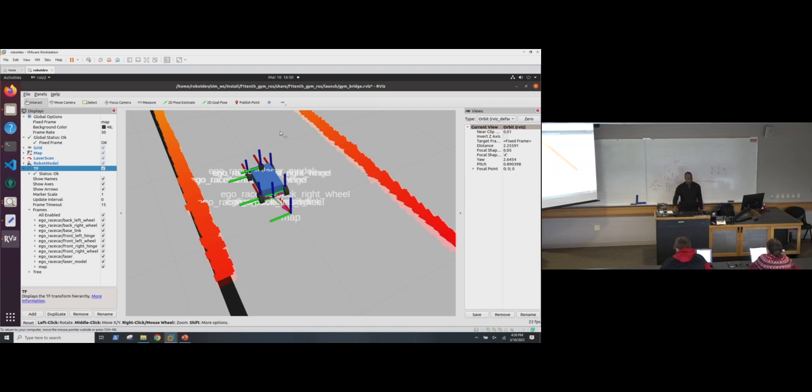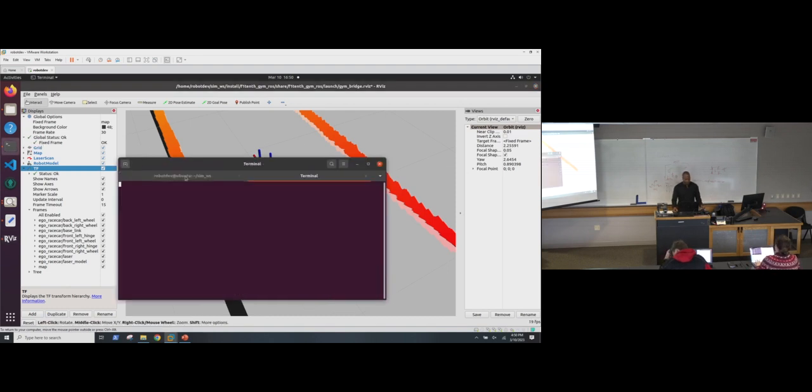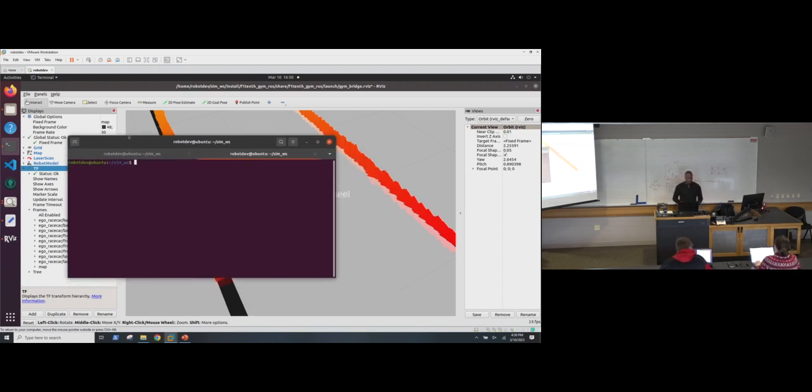So once we have it up, instead of moving it with that, let's move it around with a keyboard or mouse. Once you get your robot up and connected over Wi-Fi, someone could go into the computer and just run ROS2. We're going to run this command now, the teleop twist keyboard, and I'm going to use my keyboard.